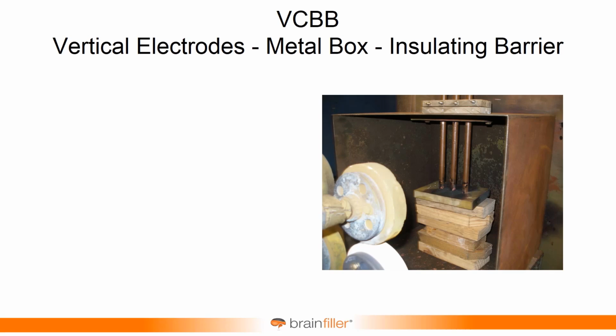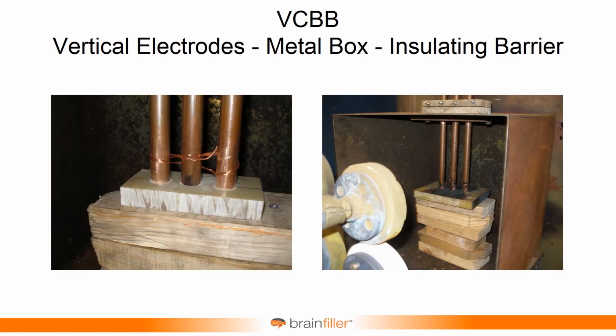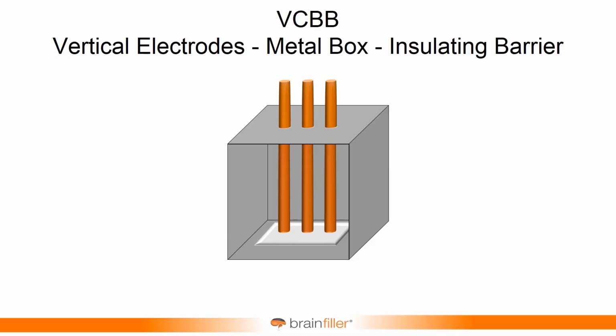And so on the left side, I show the trigger, the fuse wire wrapped around it, and then it's the fiberglass block kind of pushed up with a couple of pieces of wood, 2x4s. And so that's the setup. And my diagram just shows, this is actually more what the IEEE 1584 test was based on, what they did. And I say they because it was actually the project team that did this.